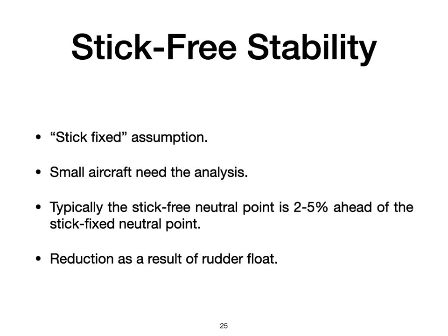Typically, the stick-free neutral point is about 2 to 5% ahead of the stick-fixed neutral point. Stick-free directional stability is also reduced as a result of rudder float.